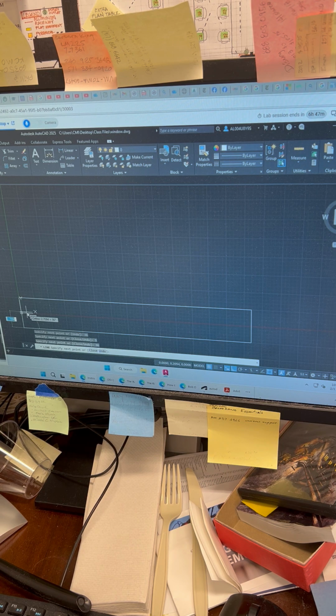All right, now you're going to point your cursor straight up, 90 degrees, and you're going to type in the direct distance where we started this whole thing. Same thing, half the width, which is 2.5, and hit enter. Now, to finish this off, we're going to draw a third line that's 36 units.